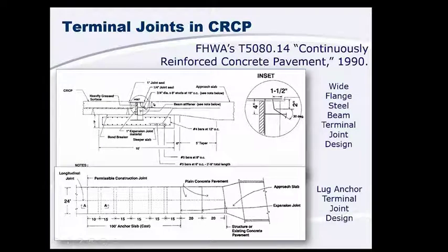And that CRC section is actually extended under the beam there. So this provides room for the continuously reinforced pavement to expand and contract independently of that other pavement without causing any damage to that other pavement. And the steel beam is actually held in place very well by that anchor down there.